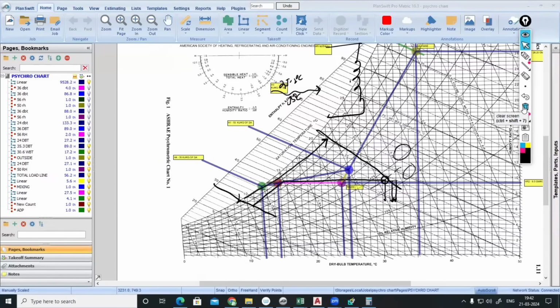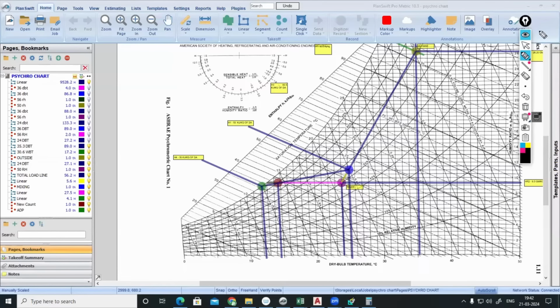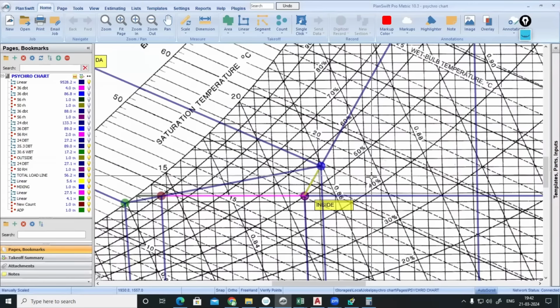If you want to find the density, on what condition the air is, how can we find it? We already studied in psychrometry. Specific volume we can find from here, and from here as well. On what condition the air is entering into the cooling coil, that specific volume we should find. Specific volume of this condition. So specific volume of that is how much?